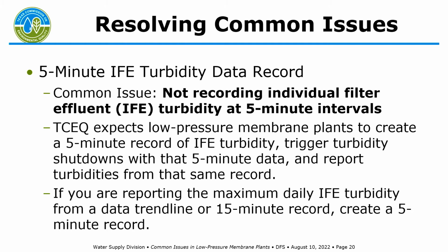If you're actually reporting your maximum daily IFE turbidity from a data trend line or a 15-minute record, et cetera, that's not compliant, and you really need to create a 5-minute record. So the turbidity shutdown, this is how it's supposed to be set up, and your plant may or may not be set up this way.